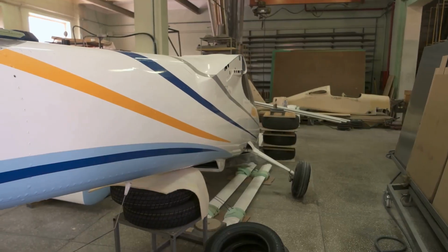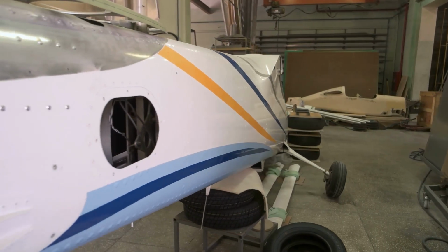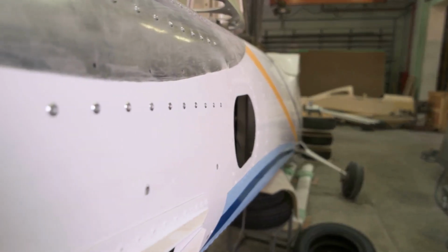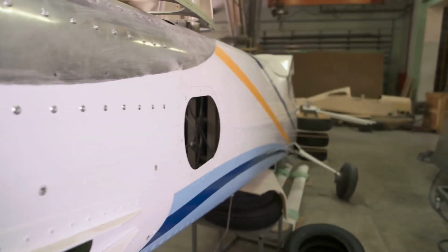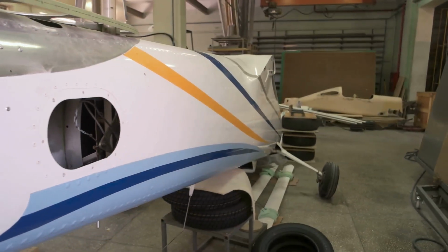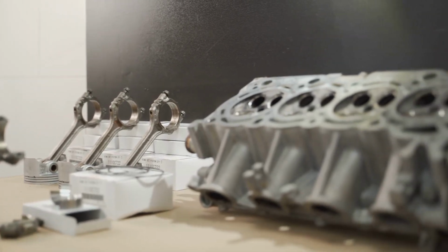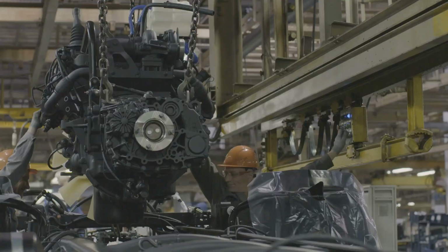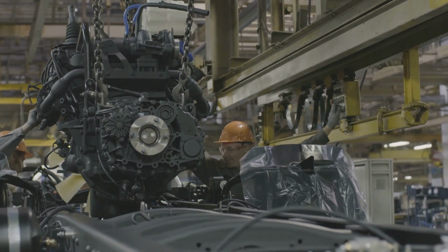Aerospace components such as fuselage cutouts or landing gear parts often involve complex geometries and load histories where local yielding is a key concern. The epsilon n approach is indispensable for ensuring their integrity under demanding operational conditions. In the automotive world, many components are prime candidates for strain life analysis. Consider engine connecting rods, crankshafts, or suspension parts.